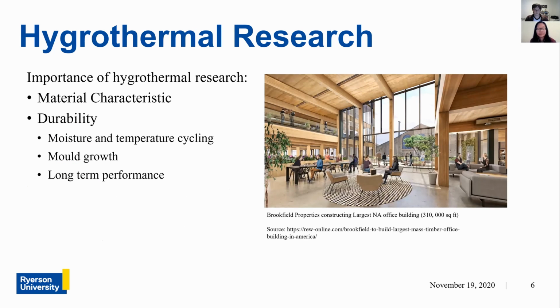The reason why hygrothermal research is very important is because overall this product is made out of wood. If you have water in it, there's going to be moisture transfer, there's going to be heat transfer. And what ends up happening is with certain temperature, certain moisture content, you end up getting mold, and that is bad. That's the whole purpose of doing this research.